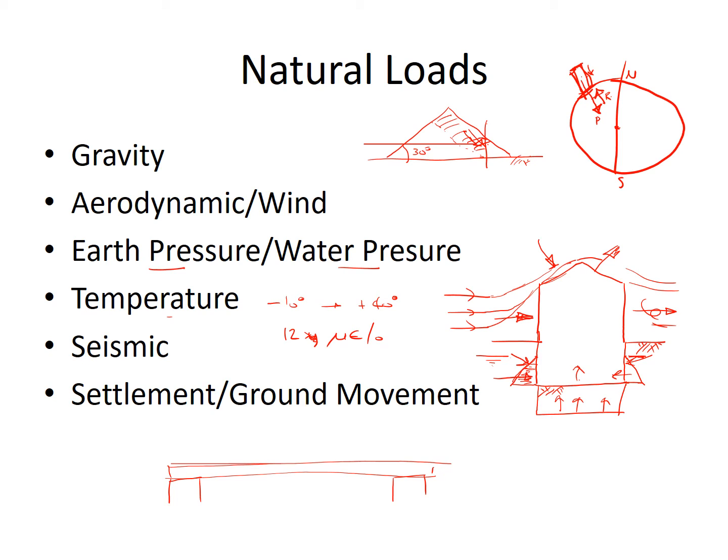And what that means is that for every degree change in temperature, we will get an extension which is 12 microstrain, which is a fraction of the original length.